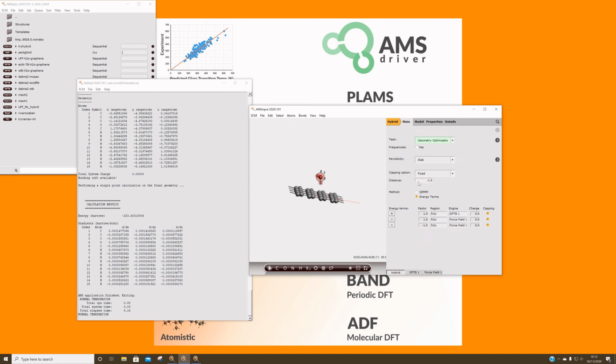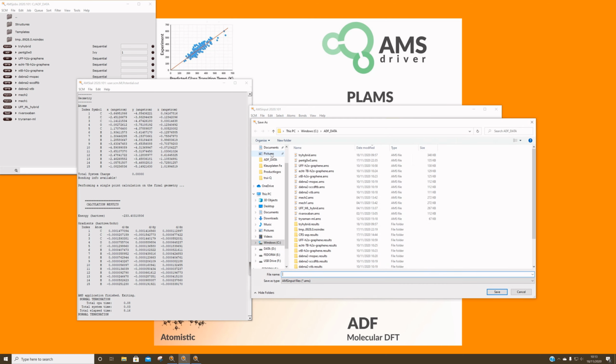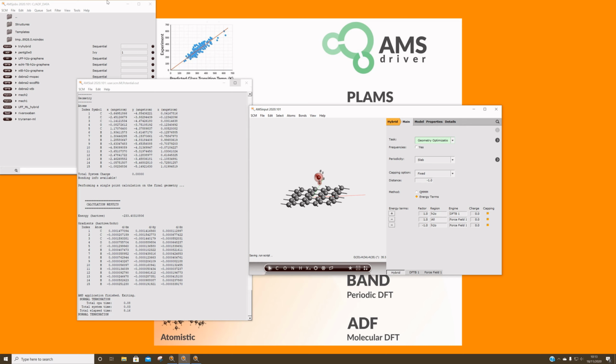panel, then okay, we do a geometry optimization. We calculate the energy of H2O at GFN2-xTB. We add the energy of the entire system using the force field, and then we subtract the energy of water at the force field level. So we avoid double counting. Let's save this as water graphene and run that calculation. Job run.